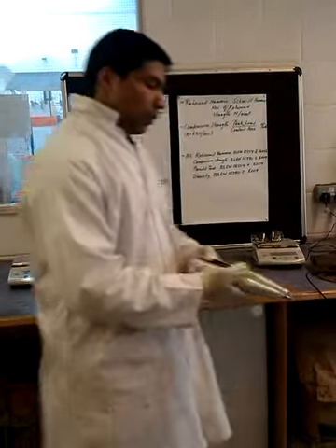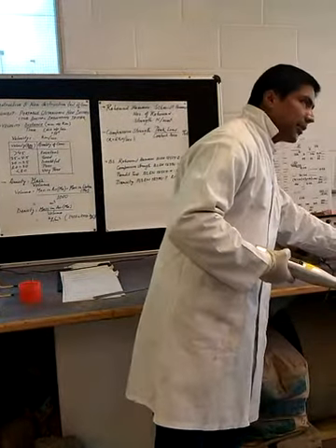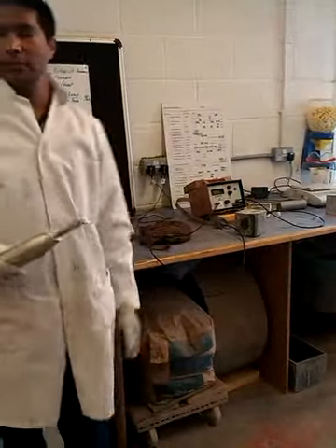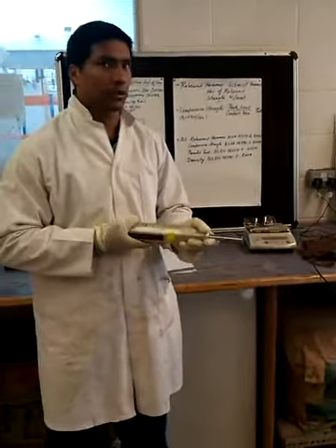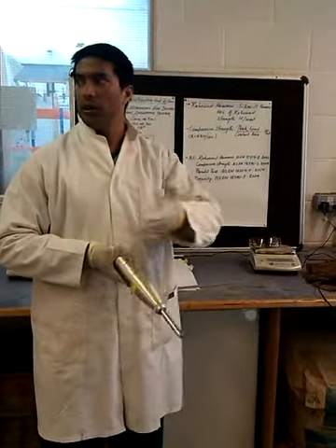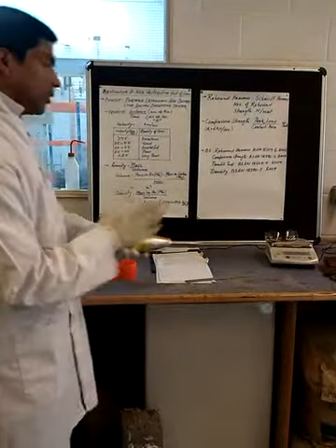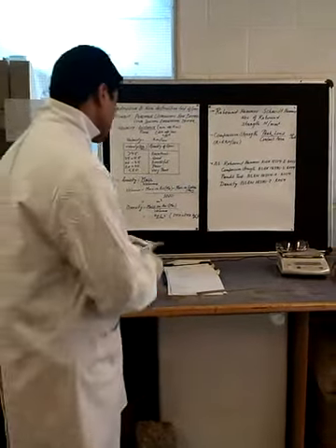Okay, so only thing is that when you use this hammer, the sample needs to be fixed. If you are not fixing the sample, you cannot get this one, right? Because it will move. So what we need to do is keep that sample in the machine, and once we load some load on the cubes, then we're going to apply this hammer to get a certain rebound number, and we'll convert it and check by how much those two are different. Okay, so that's all about the rebound hammer. Any questions regarding this one? Rebound hammer. Okay, that's fine.